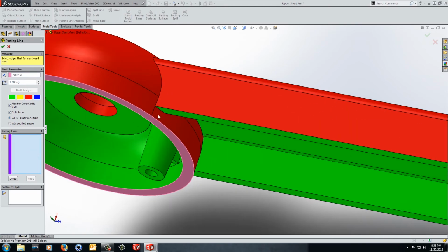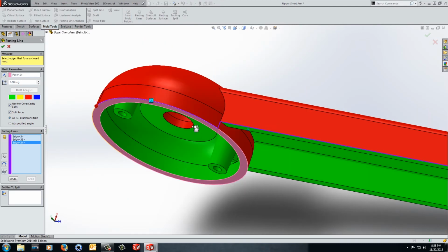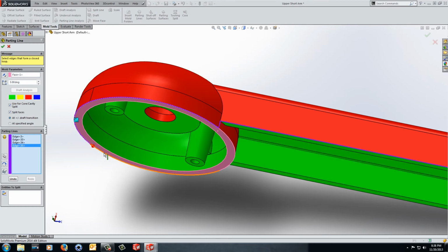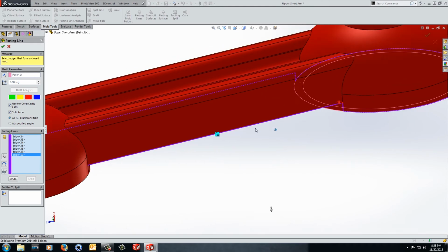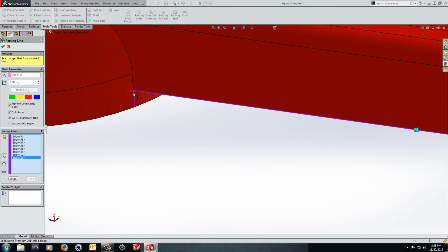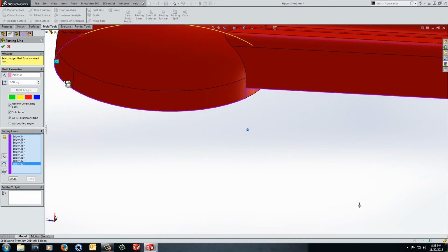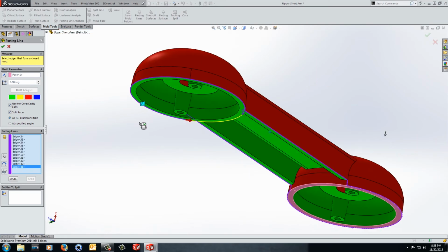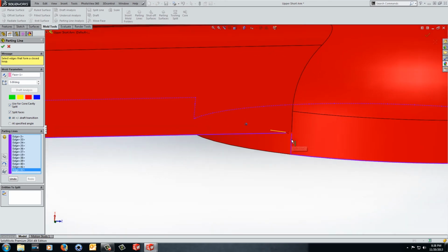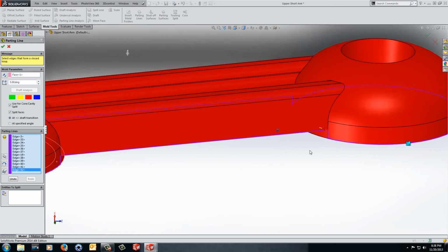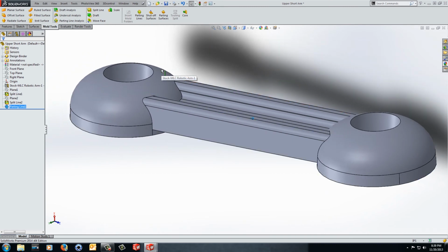And even though it's going to take a little time, I'm going to do this manually. And this is exactly why we created those planes and why we split this geometry up, because we want to make sure that we're selecting the exact geometry for the parting line that we want to use. If we didn't split these originally using the planes that we created, then we wouldn't have this selection process here, and that would just make this a little bit more complicated. As I mentioned, that split faces option isn't going to produce the type of split that we wanted in this case. So now that we've selected all the areas that we need for our parting line, I'm going to go ahead and hit OK. So now we've got a parting line where we want it, and everything's looking good here.